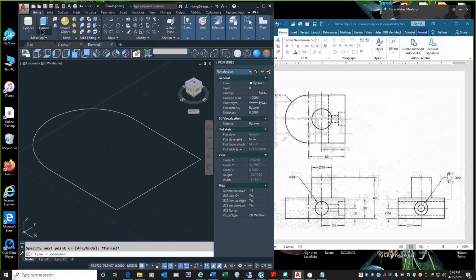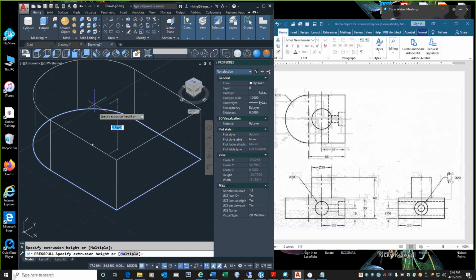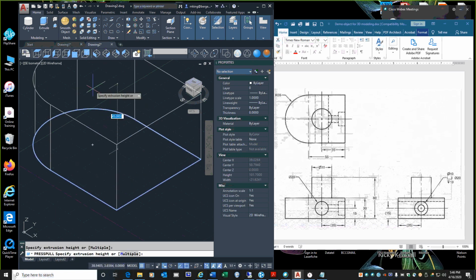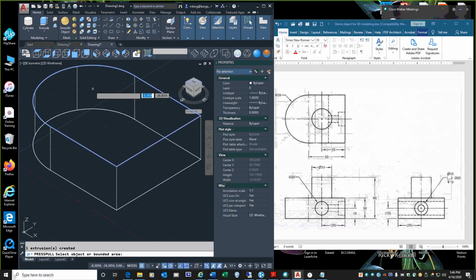Because I've scrunched my screen down, I don't see the names of this, so I picked that up on myself. Press pull. So I'm clicking press pull, putting my mouse inside the shape and clicking, lifting up and saying 30. 30, enter. And then a second enter to complete. Remember, it's 30 inches tall, from here to here. And now I have that whole shape done.